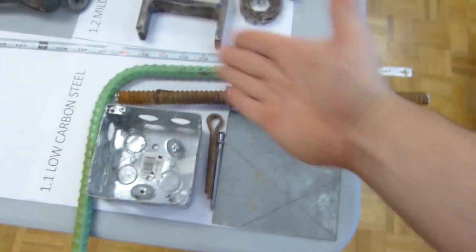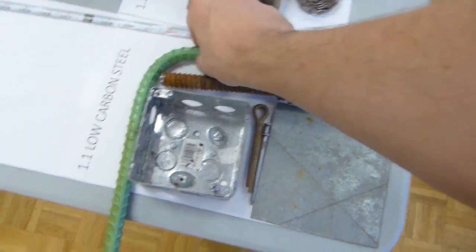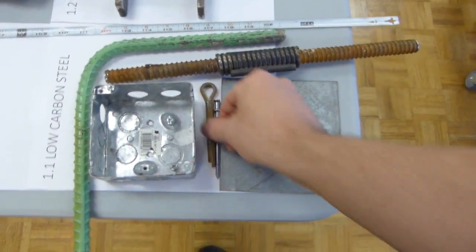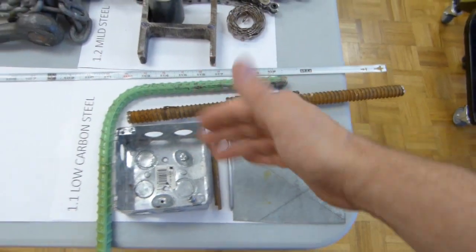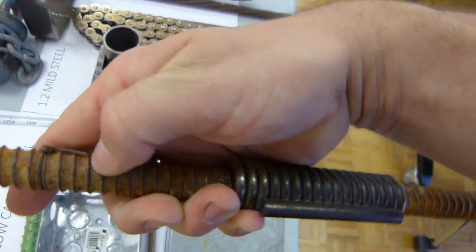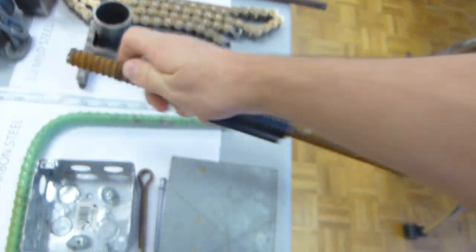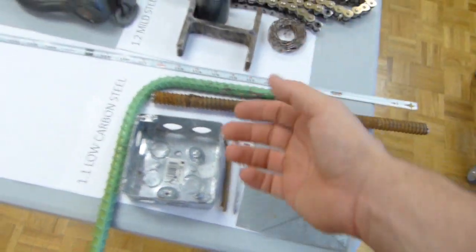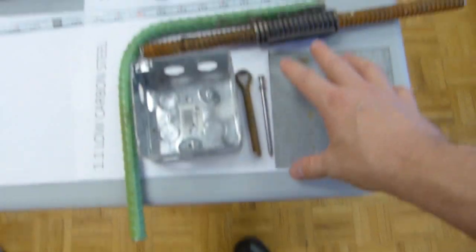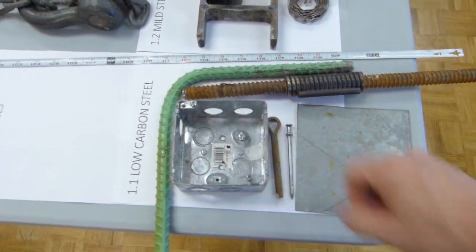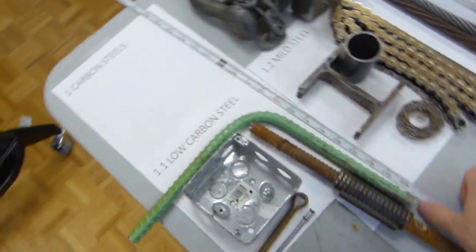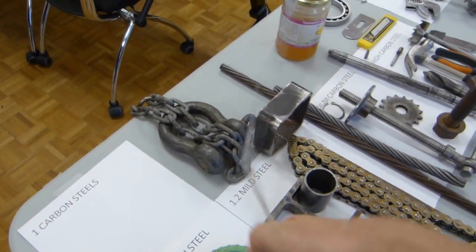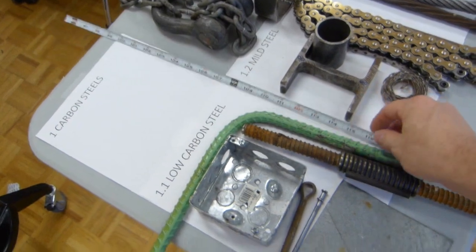So the point of this type of soft metal is that when you make bends with it, they don't break. They don't crack out here where the bend is the strongest. So you can repeatedly bend them over, same as with a piece of tie wire. That's why I have this one with a little piece of tie wire left on it. Whether it's sheet products or wire products, these are also wire, just thicker. They are very soft and they are readily weldable with no precautions, no concerns, no nothing. I also have here a piece of tape measure. Of course, you can tie a knot in it, maybe not with one hand, but you get the idea. A very soft form of steel.